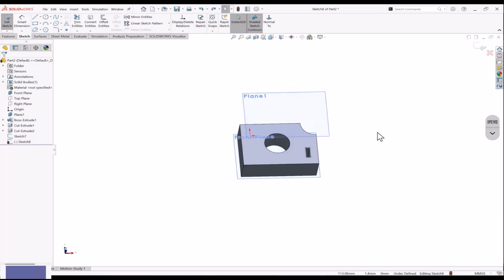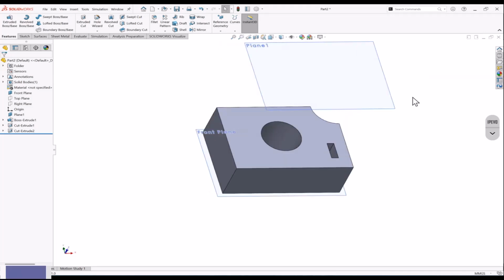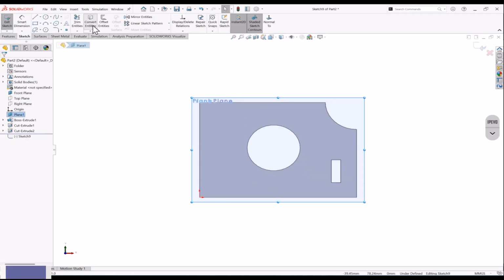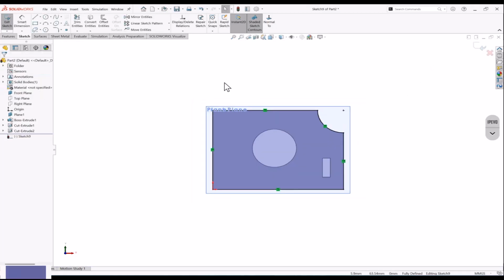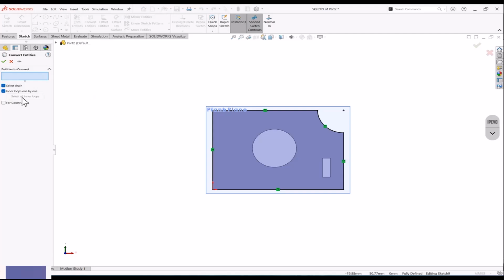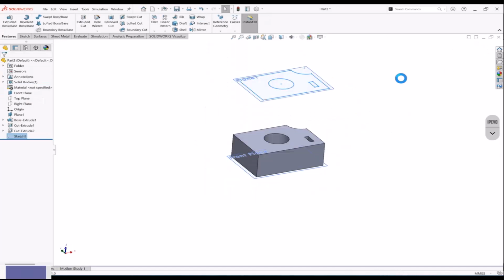Or like you need the complete one in a single click. What do you do? Let me do undo a little. Get back, select this plane, sketch on it, and go to convert entities. Now select this inner loop also. So the software will automatically detect the loops for you. Now click on the body and do okay. Oh, it's not detected, then we have to do it manually. If not detecting, then we have to do it manually. So it should do, but it's not done. Let's select it and I'll select this and do okay. Now why did I tick the inner loop? So I click on single, it's selected, see, together. Okay. This way. Now you can use it.